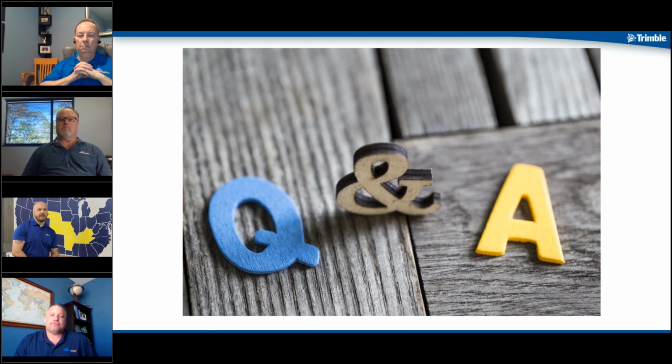Very good. And I'll add, depending on if you've got a CAD drawing that has the curve identified, depending on how that curve is identified, you can, as we've covered before, and we're going to talk again here in a couple of weeks, just how to create data. If you're using Trimble Field Link and it's a true radius, as I spoke about earlier, you can find that point. If it's a segmented line, you can use the segments and have lines within each segment.